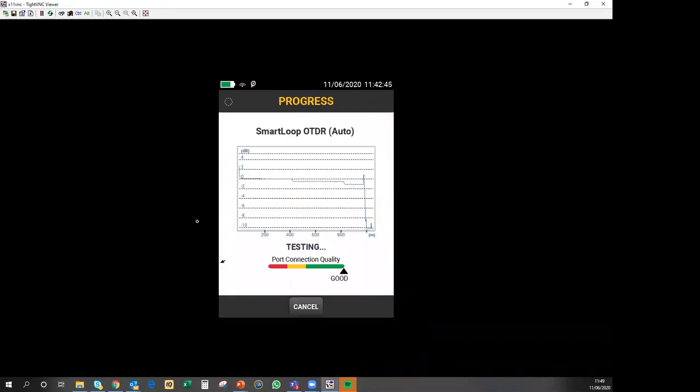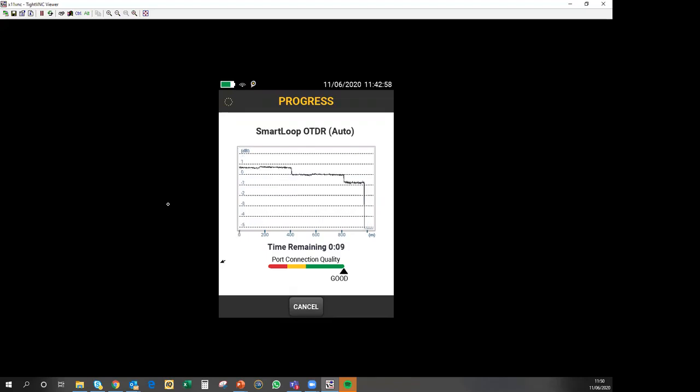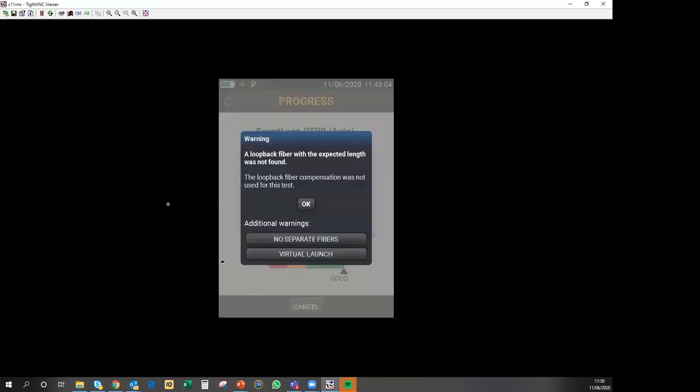You'll notice that in the picture, there is a small sacrificial cord in there. That is the port saver. That is there to protect the port so that we're not constantly plugging and unplugging potentially dirty cords directly into the optics of the OTDR. So I've reversed the cords, I can hit done, and the unit will go away. And in another 13 seconds or so, with a bit of luck, yeah, 13 seconds will provide us with a second test result for these two fibers.